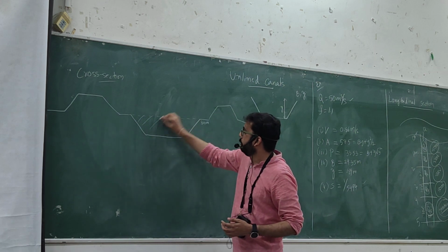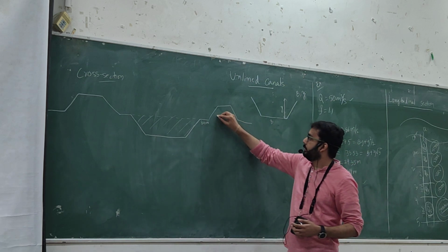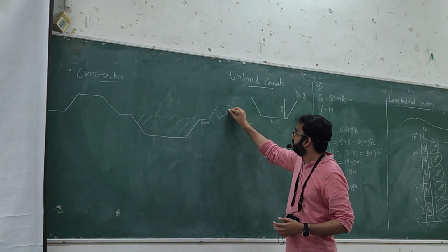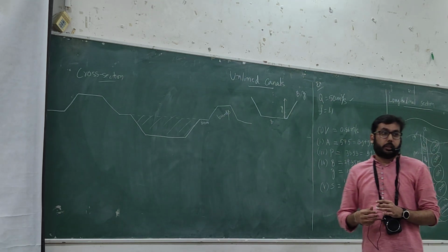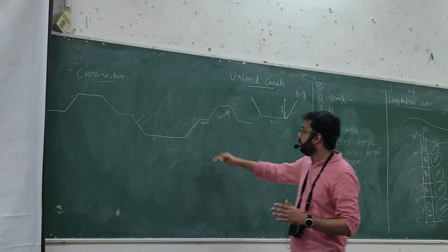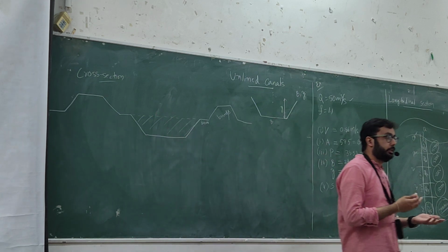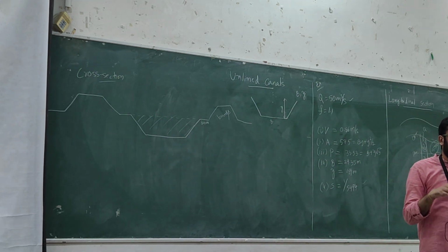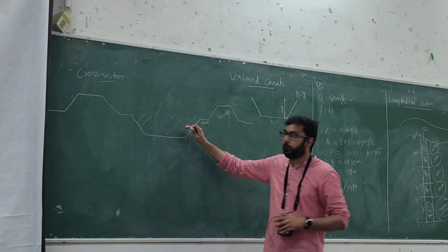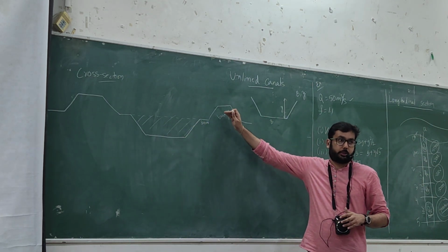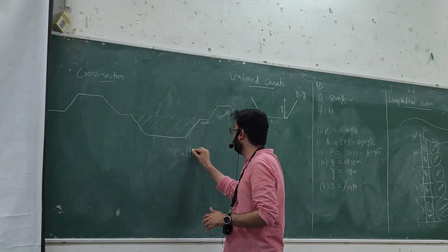So this is our canal through which the water is flowing. And these are the banks. Now in some locations, because we are designing a trapezoidal section, we have to cut the land in some places and we have to fill in some places. And whatever we cut from the canal section, you can use for filling in the banks as well, right? So we have two processes that we need to do, cutting and filling.